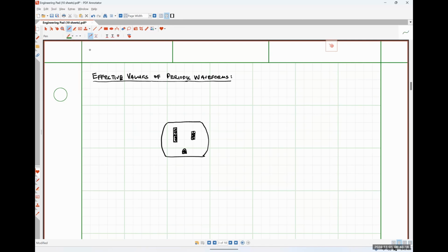This bottommost pin is typically connected to a green wire inside the walls of this building. And this is our ground wire. It likely connects up somewhere inside our load center, or what you more commonly call a breaker box. And then that connects to a ground pin outside your home that is literally a metal stake buried in the ground, to give the potential of the earth as the reference for all of the voltages in your home, if your house is grounded correctly.